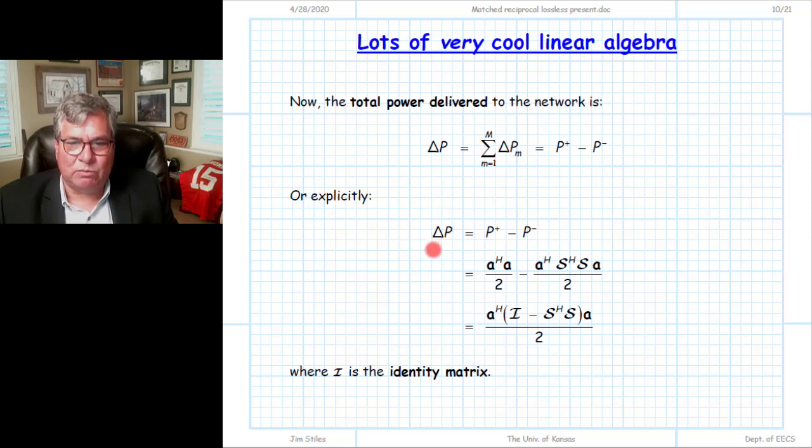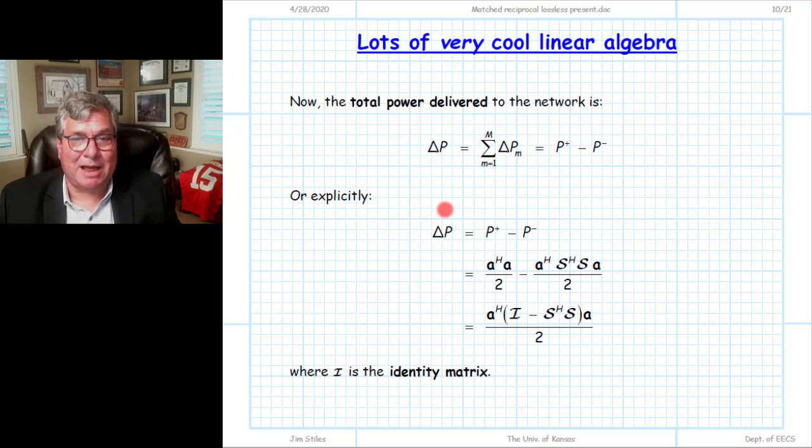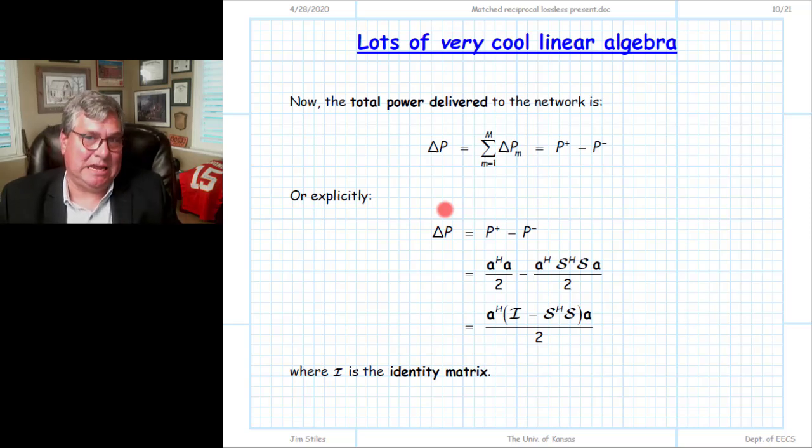Now, the important thing here is to understand what this net power flow is. If this net power flow turns out to be positive, that means that energy, the net power, is going into that device. What happens to it? Well, if the net power flow is positive, that means the device has to be absorbing that net power flow. Every second we have 23 millijoules of energy that flow into this device, the net. Yes, we have things flowing out as scattered and things coming in as incident. But if we take the difference between the two and that result is a net positive, that means stuff is going in. The net power is going in. It has to be absorbed in that case.